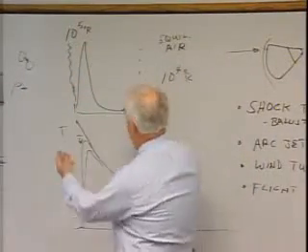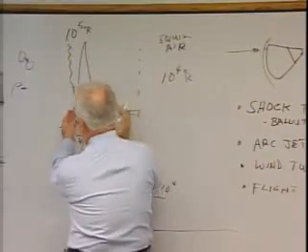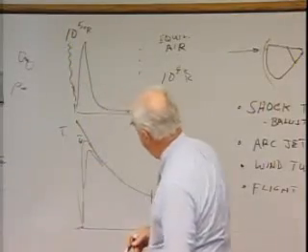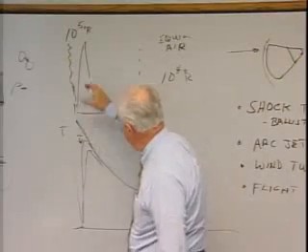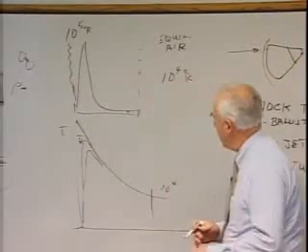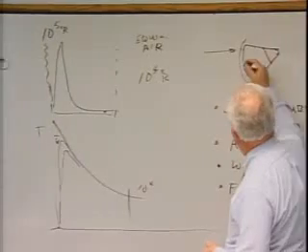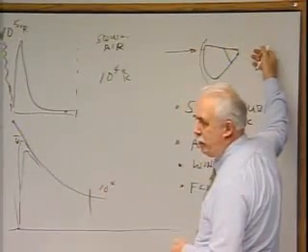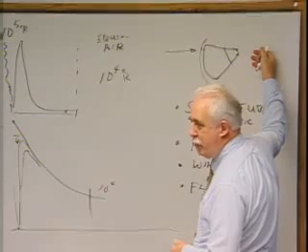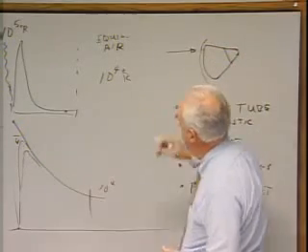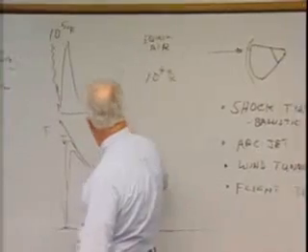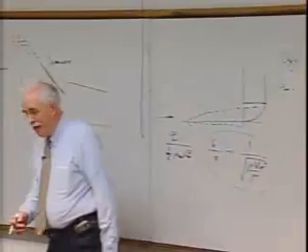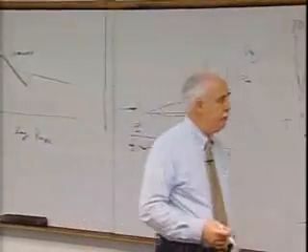Now, some people might call this effective shock thickness, but I term the transition to higher temperature the shock thickness, and then the relaxation, a relaxation distance. At altitudes above that, the flow could be completely out of equilibrium. It hasn't gotten back to equilibrium because this characteristic time is directly proportional to pressure, which, and I erased it, is directly proportional to free stream density.